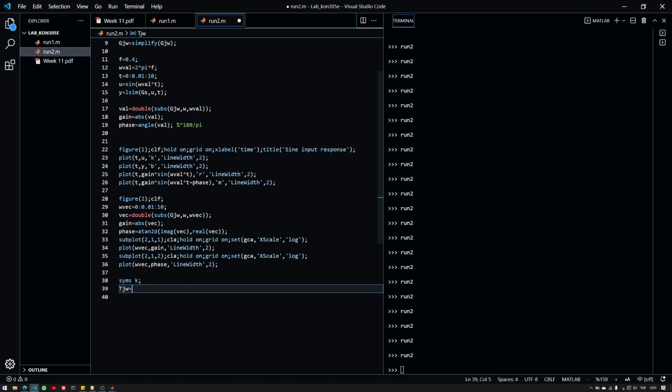So you can use K times G(j omega) over 1 plus K times G(j omega). The reason I can do this here is that I'm using a P-type controller, which is a static gain. If it had any s term in it, I would have to substitute s equals j omega into it again. So now this is T(j omega), and since K is real, I can also type it out.